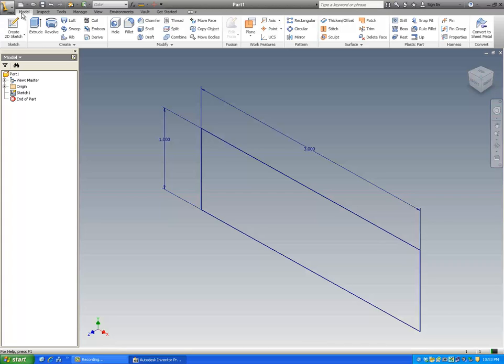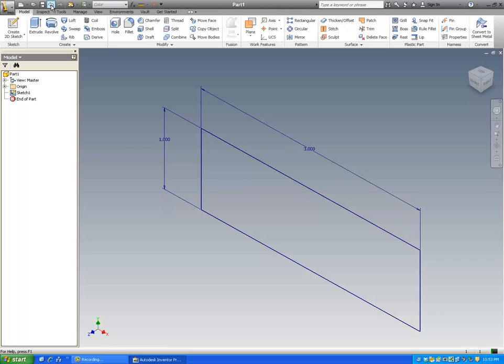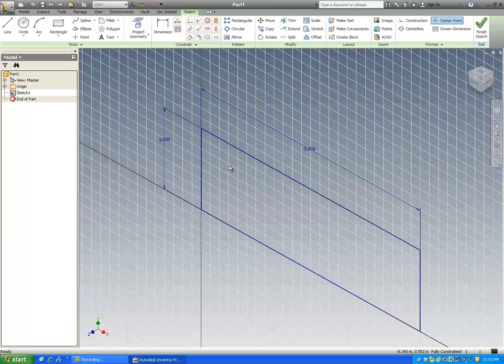What we will do over and over and over in this beginning episode of 3D modeling is I will extrude my object. It will default to picking that one profile that I had. If I go back here, do the back button up here, this is the one profile I have. It's also called a closed loop, which is very important. This is one loop. If it's not a closed loop, you'll have problems when you start to model. Okay, so I have to finish the sketch again.